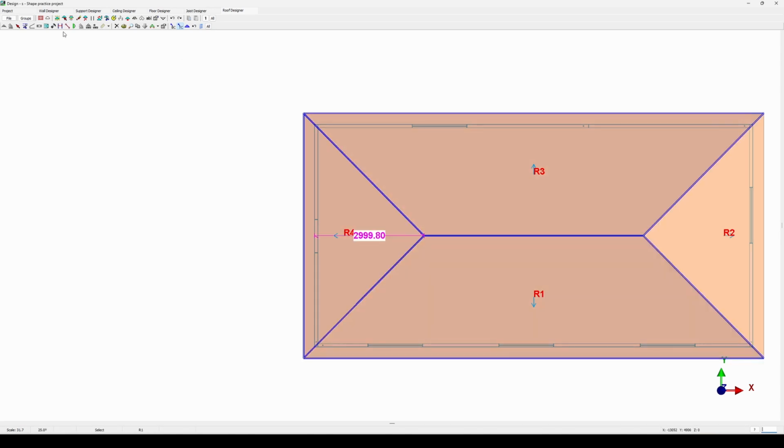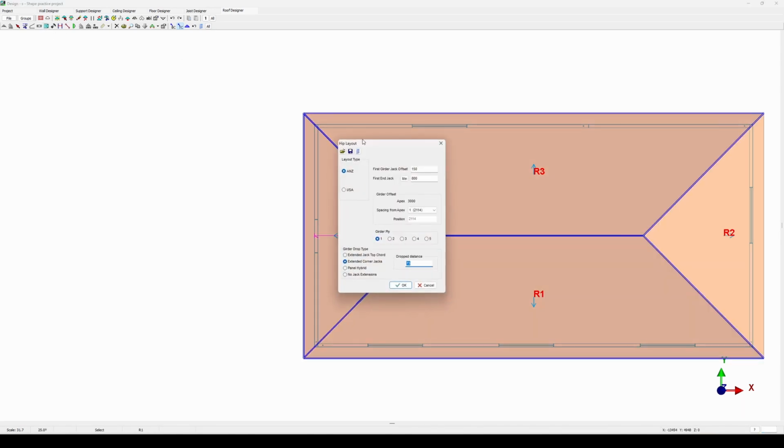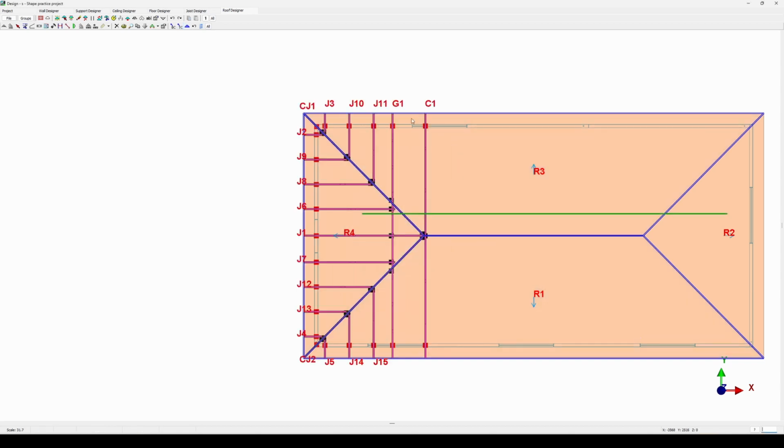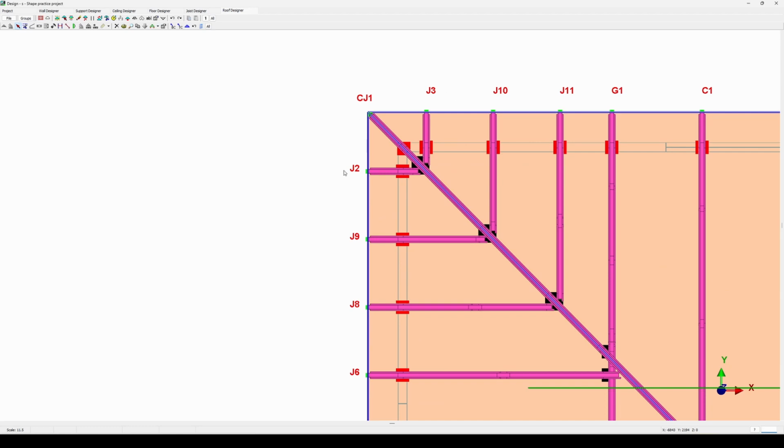Redo the selection, auto hip this project, and I'm going to click on minimum, and you'll see it automatically corrects that dimension to use the 200 millimeter minimum span for the truss. Click OK. And you'll notice this is now a lot closer to the end of my overhang, with the measurement now being taken from the edge right there to the center of my first jack truss.